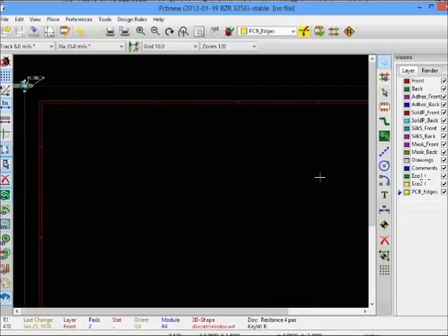Now these are all the layers that we're going to use on the PCB. Now I've chosen a simple 2-layer board. In fact, we'll do a single layer board because there are hardly any components. So these are the front layer, then the back layer, and all the other options. This silk is for writing text on your PCBs, so it could be on the front side or on the back side, and these are various other options. We'll see them as we use them.